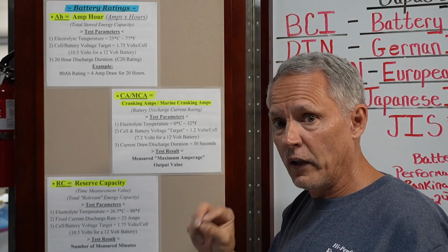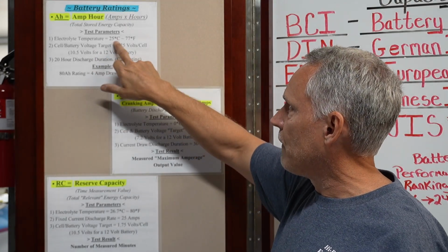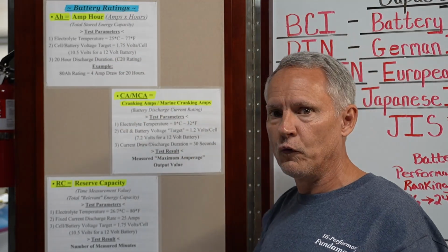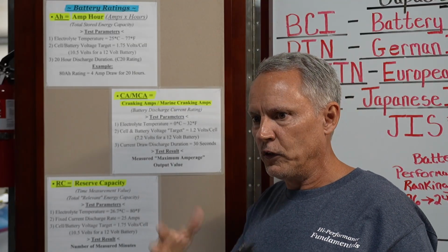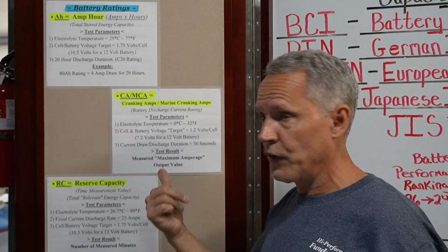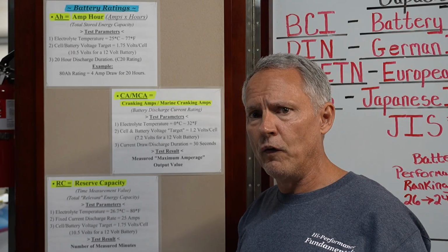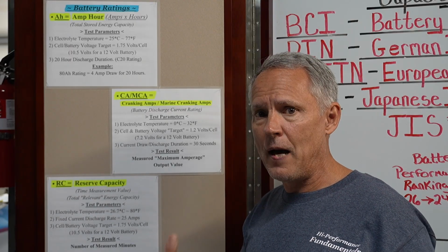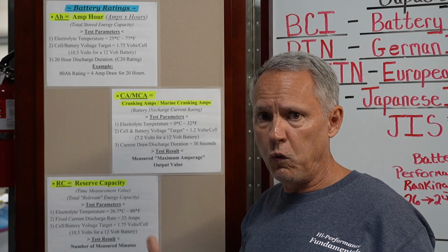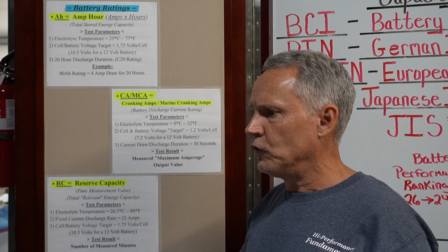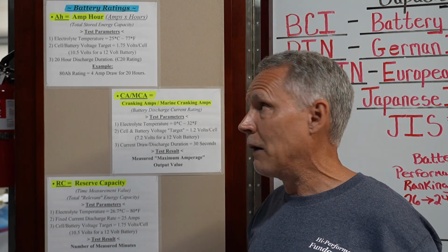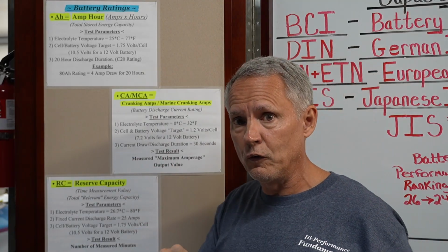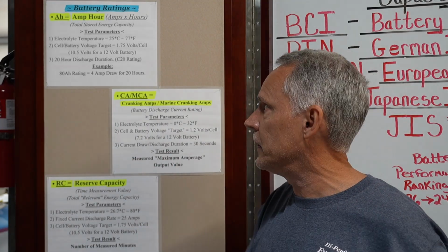When I started the test, we would have been at 25 degrees Celsius or 77 degrees Fahrenheit. So the battery is fully charged, right? And a battery that you just charged would be hotter than that. So now that we know the battery has been fully charged, it's had time to settle, which can be as long as 12 hours or sometimes even more, so that the battery voltage has stabilized. We then start the test with the battery at about 77 degrees Fahrenheit, or 25 degrees Celsius, or about that.